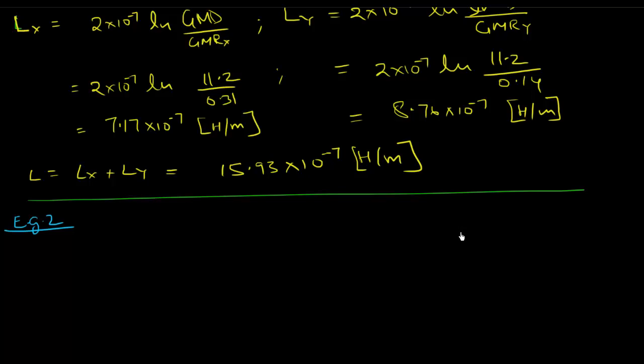So imagine it's not a composite conductor, it's a solid conductor, similar to what we had been using in our discussions earlier on inductance. And the distance between these two is D. The radius here for this conductor is Rx, and the radius here is Ry. This is conductor X, this is conductor Y. Again, still a single phase circuit. So this has current I going in, and this has current minus I coming out. What's going to be the L value here?